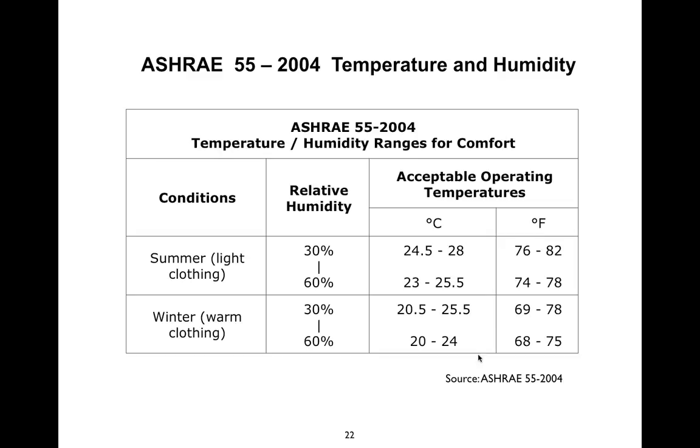No, chances are the humidity in your home right now is probably under 20%. Could be 10%. Unless you're humidifying, the air in your homes right now is very dry. The reason for that is that air, depending on its temperature, can hold a different amount of moisture. Now, if it's 50% humidity outside at 30 degrees, when that air comes into your home and you heat it up, the amount of moisture that it can hold is much higher. So, it has the same amount of water in it, but relative to the amount that it can hold, it might only be 20% or 10%.